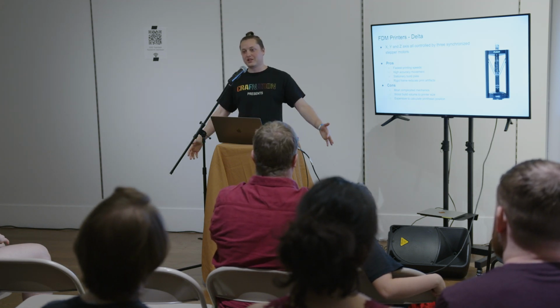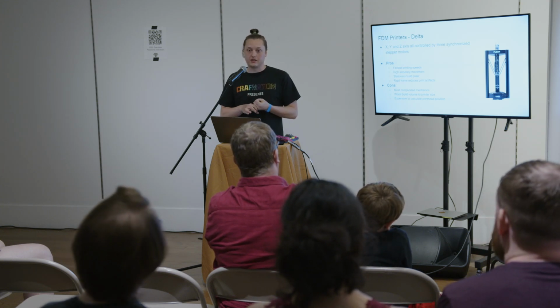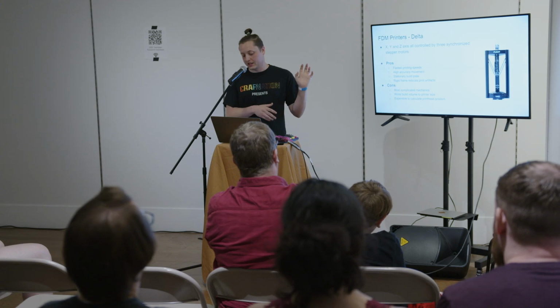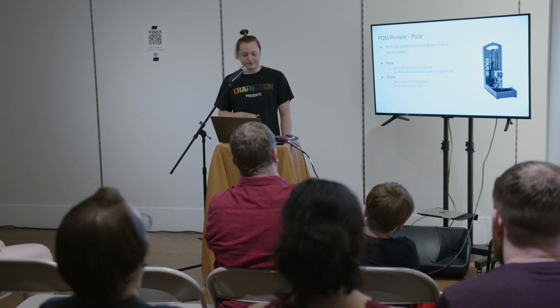The cons are, it's the most complicated mechanics. To build a good print volume, the printer itself needs to be about 3 times the size of the print area. So you start to get really huge, tall printers for not that much more space than you would get with the Core XY style. Due to the way that it moves, it also needs to do a lot more computing, so you need much higher computing power to do the slicing and the printing with these. It's expensive to calculate the print head position.